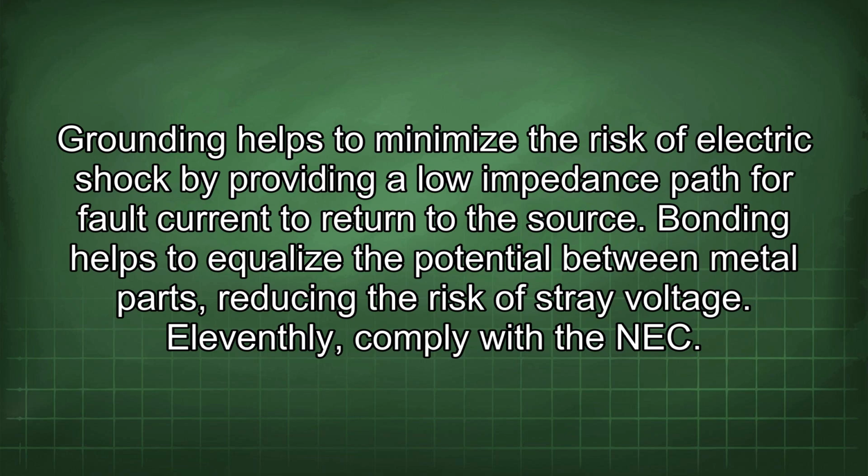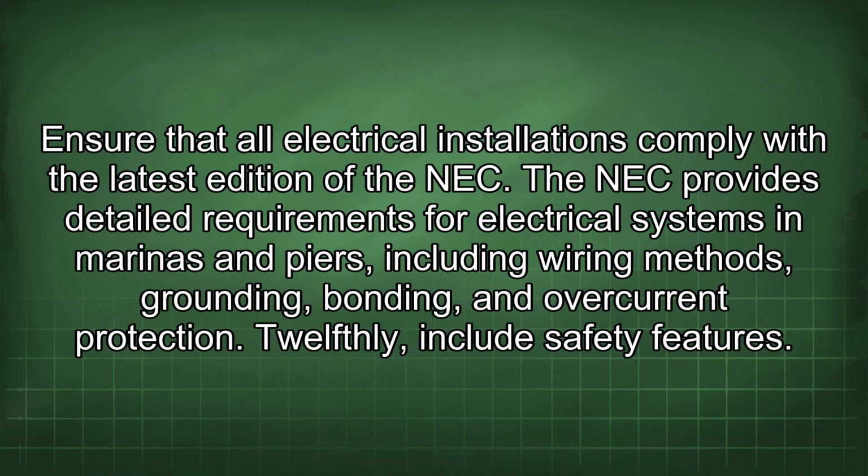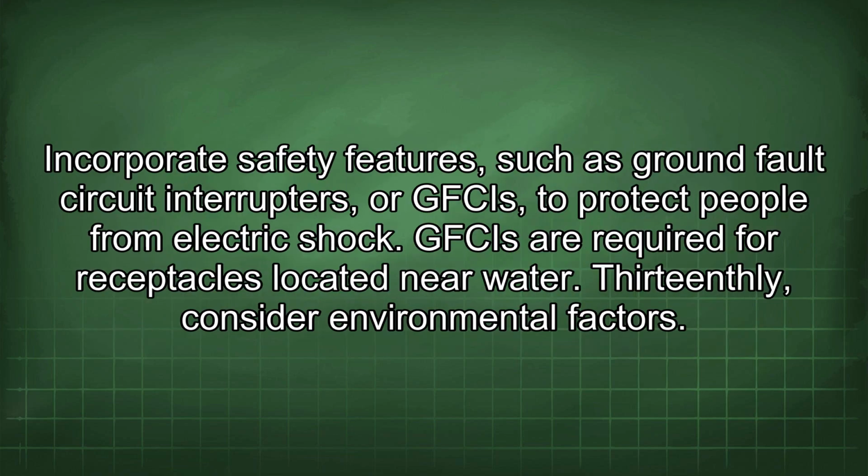11thly, comply with the NEC. Ensure that all electrical installations comply with the latest edition of the NEC. The NEC provides detailed requirements for electrical systems in marinas and piers, including wiring methods, grounding, bonding, and overcurrent protection. 12thly, include safety features. Incorporate safety features, such as ground fault circuit interrupters, or GFCIs, to protect people from electric shock. GFCIs are required for receptacles located near water.